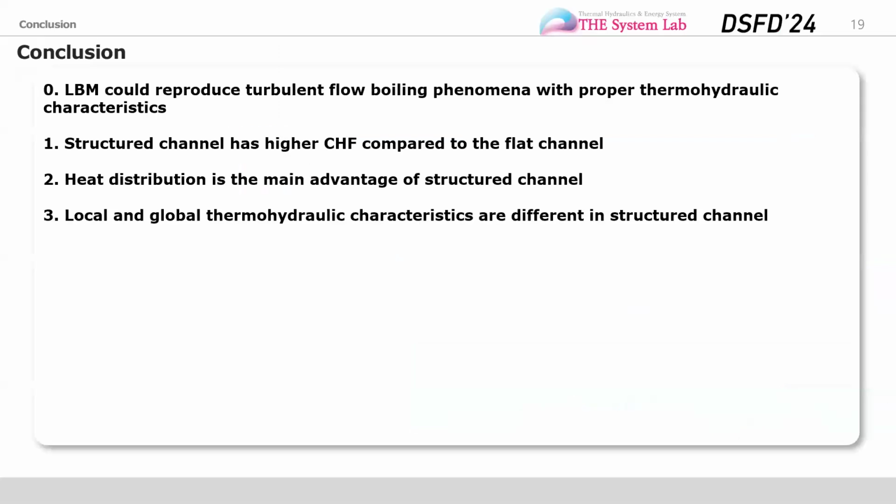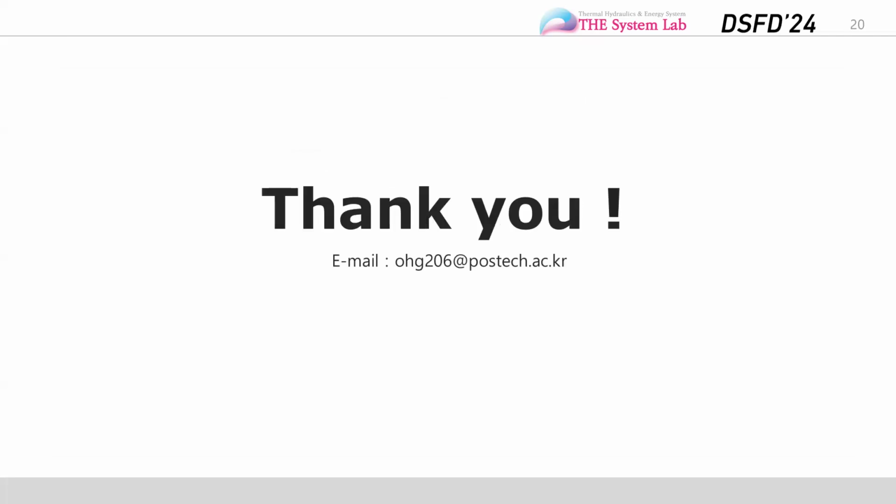And this is my conclusion. LBM could reproduce the turbulent flow boiling phenomena with proper hydraulic characteristics, and the structured channel has a higher critical heat flux compared to the flat channel. And heat distribution is the main advantage of the structured cooling channel. And local and global thermal hydraulic characteristics are different in the structured channel compared with the flat channel. Thank you for listening.